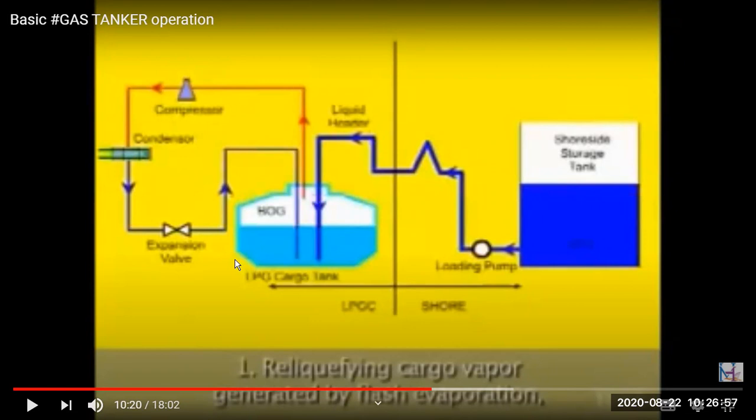that we have already seen. Now on the refrigerated ship, we load. We came out of the dry dock. We did the inerting. We take out the inert gas by putting the vapor in the tank, gassing up, then cool down the tank with some liquid, and now we are loading the cargo. Now, whenever we are putting the cargo or vapor in the tank, there will also be a lot of vapor generation. So that is called boil off.